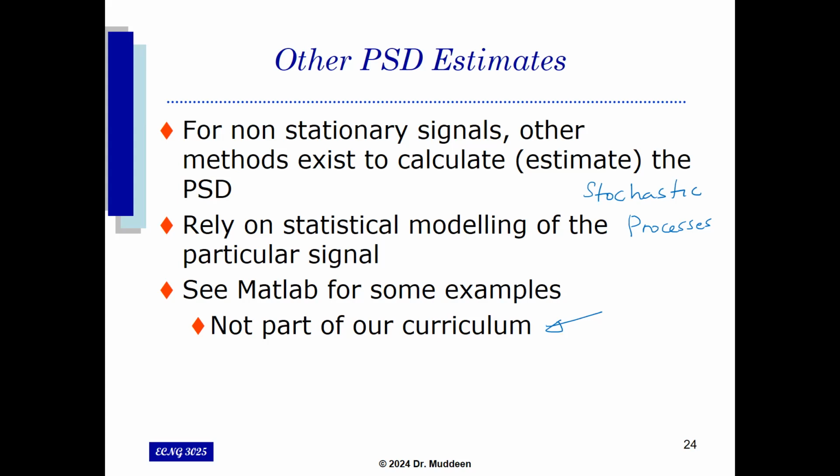What we did today is that we covered how to analyze the spectrum of a signal where the frequency content is varying with time. We call those signals non-stationary signals. And one way of looking at it is by doing something called a spectrogram. You basically divide and conquer. You take the signal and cut it up into smaller bits, look at what each bit is doing, and then reassemble the answer. In doing that, you sacrifice resolution because you look at a smaller number of samples at a time, but the big picture allows you to see some quite interesting features that you can't see normally.